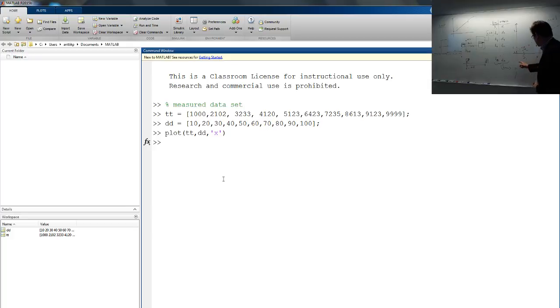First thing, let's calculate the parameters for the first degree polynomial with polyfit. I need to check polyfit. Help on polyfit: x, y, n. Yes, that was it. So always such that your x is the measured value, and y is in the units of the final product.